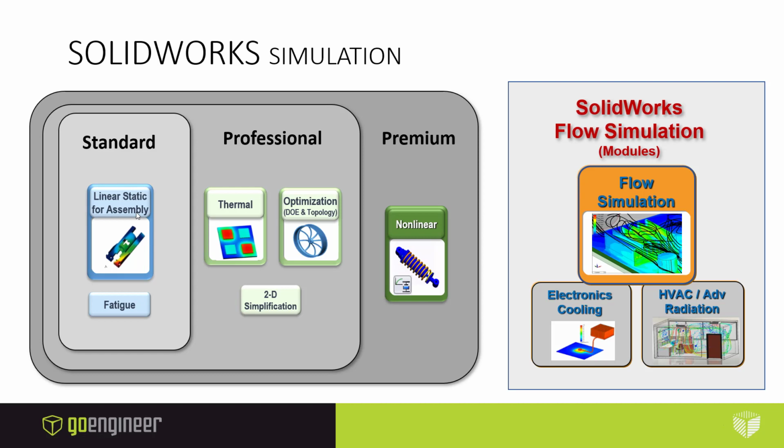Do you want to bring the temperatures in from a hand calculation and then run a static study? Do you want to bring the temperatures in from a thermal study and then run static? Or do you want to use flow simulation to do the work for you? Okay, and one of those big differences we saw was convection, those convection coefficients.